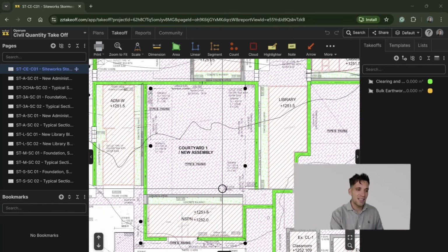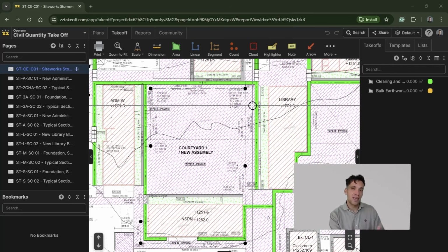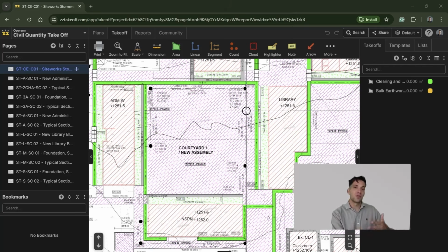But in addition to this, we'd look at things like the geotech report to understand different soil types, bearing capacity, the water table depth to determine if we're going to have to do any dewatering, whether the material is suitable to reuse, which is going to impact the imported fill volume, and any bulking or swelling factors for different types of materials.